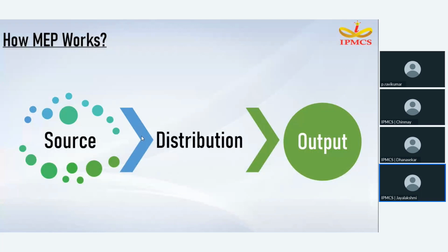So as we were discussing, the quantity takeoff is the crucial step in cost management. About 25 to 30% of construction cost is consumed by MEP in a normal construction. But if we are moving into heavy construction like factories, this can escalate up to 40 to 50%. That is a huge cost, right? So even a small mistake in MEP takeoff can have a large impact on the total cost of the project. So accuracy in the MEP estimation is very relevant.